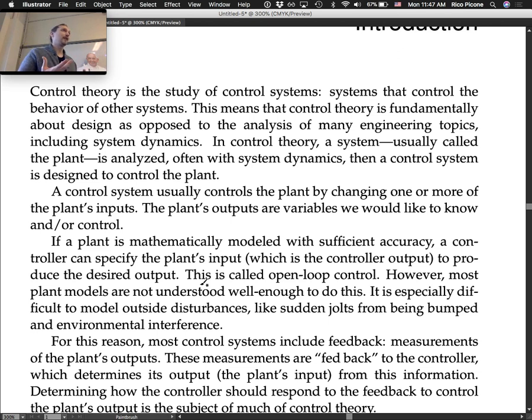Say you model it and know that if I put this voltage in, it'll be about that speed. You can do okay with that, but if things change slightly in the environment, or parts wear a little bit, or different things happen in your electronic system, or maybe the model doesn't take into account the resistor heating up and changing how much dissipation you get in your motor, then you're going to be inaccurate.